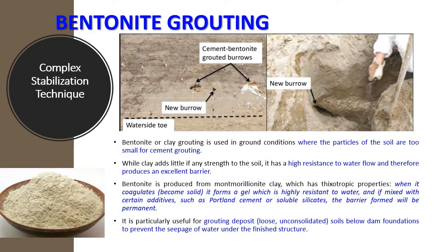Complex stabilization technique: bentonite grouting. Bentonite or clay grouting is used in ground conditions where particles of the soil are too small for cement grouting. While clay adds little strength to the soil, it has high resistance to water flow, and therefore produces an excellent barrier.